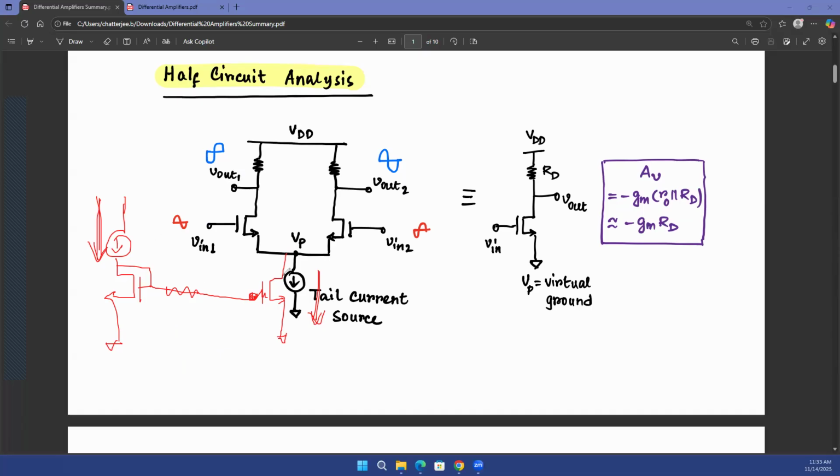The left side current still has to be the same as the right side current. And that's why you generally bias circuits with current mirrors or current sources instead of biasing them with voltages. Although voltages are easier to think about when you are doing the analysis, in real life, if you're building a chip, you'll most likely use a current source to do the mirroring or the biasing.